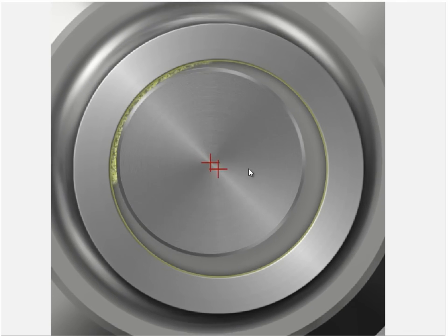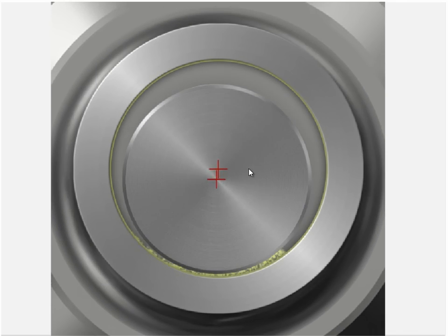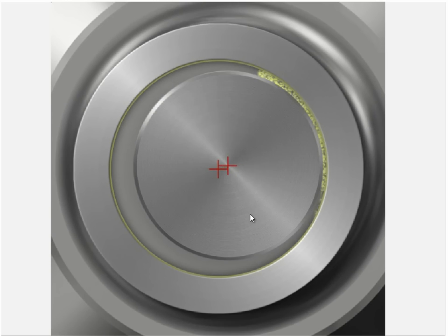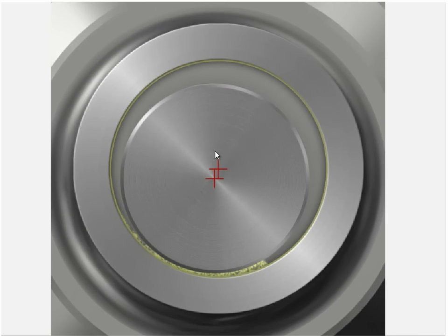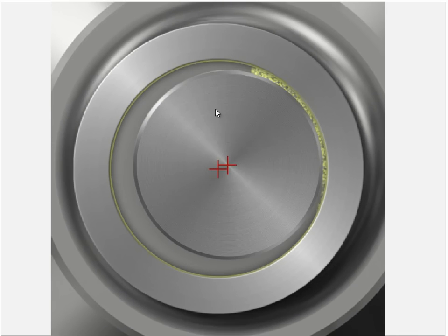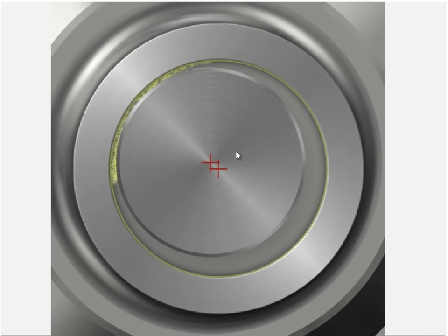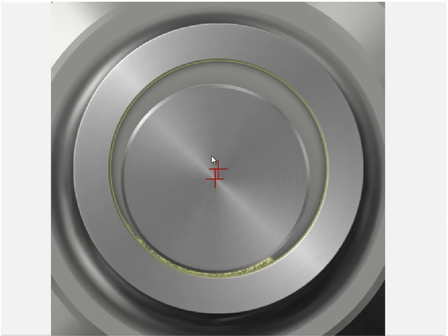It's using up all of the clearance that's available, hopefully still keeping that wedge there, but this is quite high vibration. It can't be any higher at this particular location. It can't be any more motion because it would start wearing away the bearing. But this is the sort of thing we'd like.